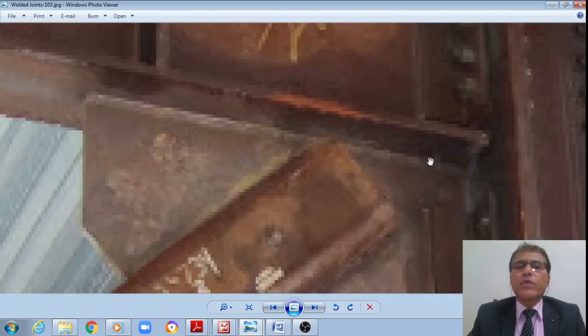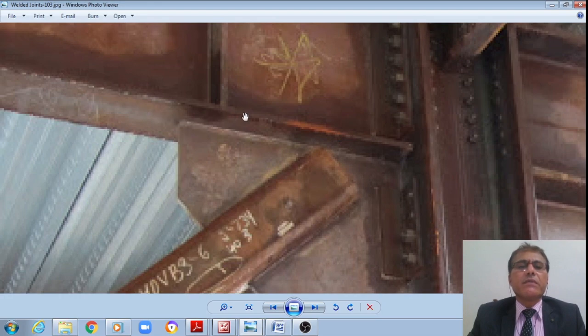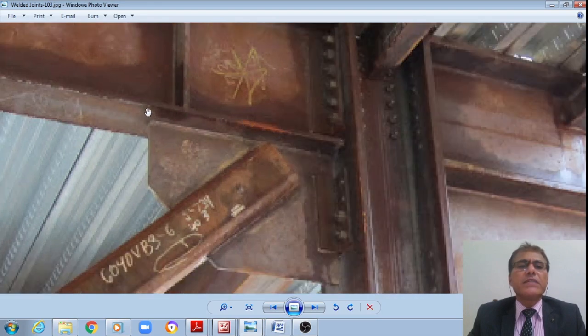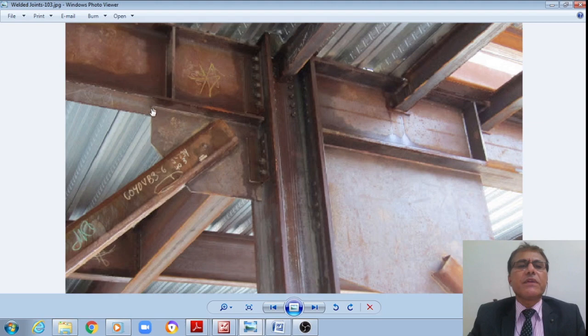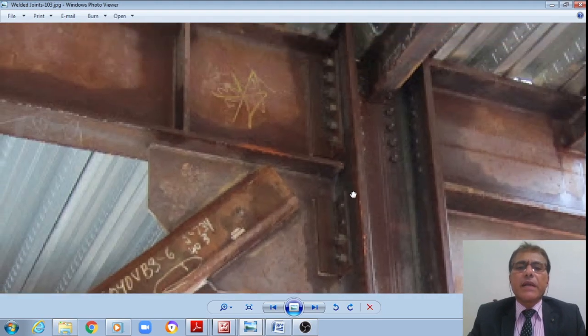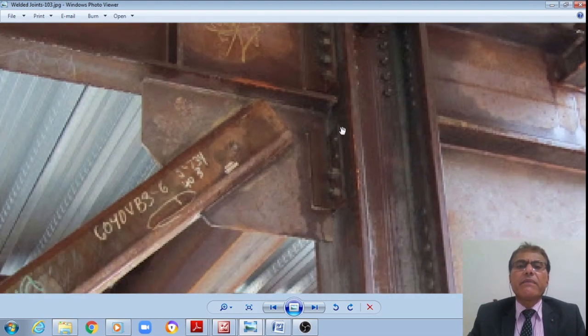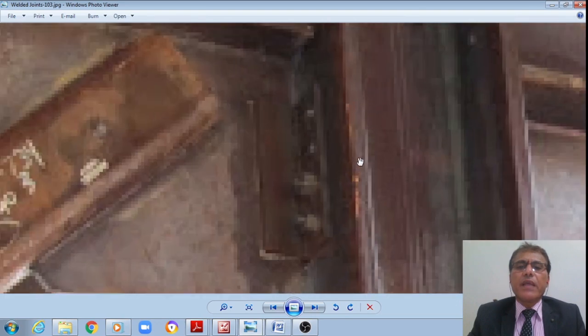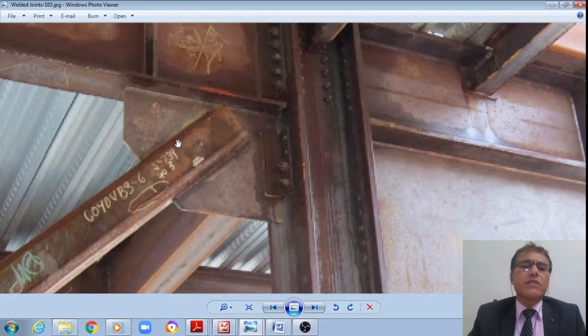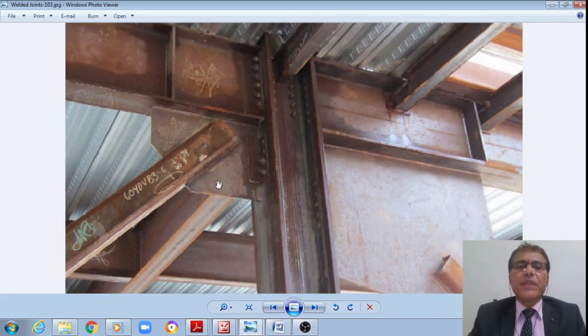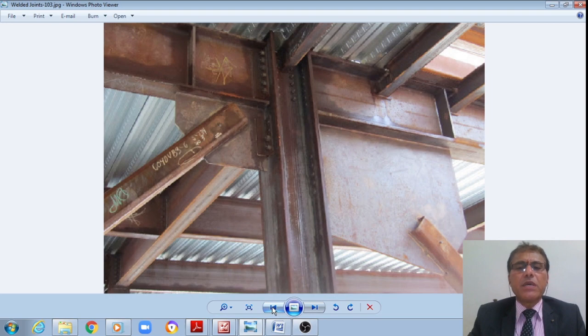You can see this gusset plate is connected to the flange of a beam. It is connected by means of welding to the flange of a column stanchion, right? That is how we calculated these overlaps. This top overlap is equal to 225 mm and the bottom overlap is equal to 115 mm. That is how the schematic looks, student.